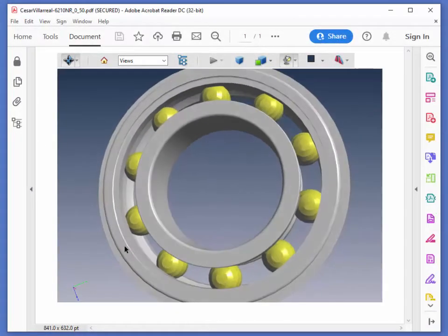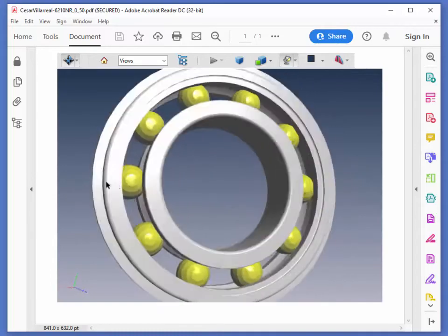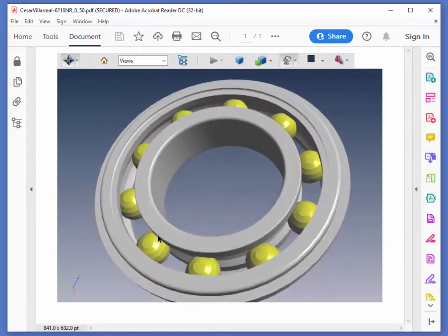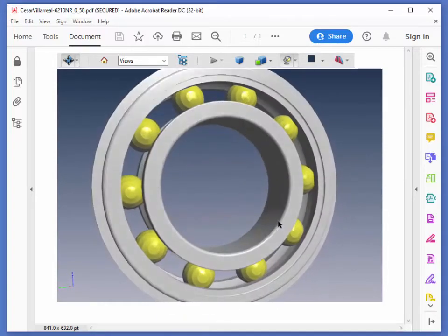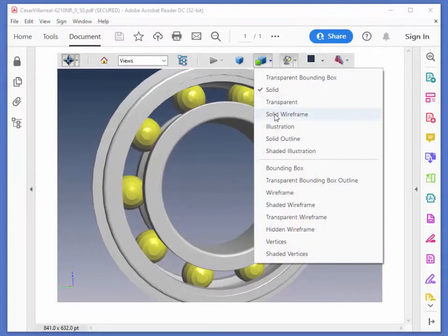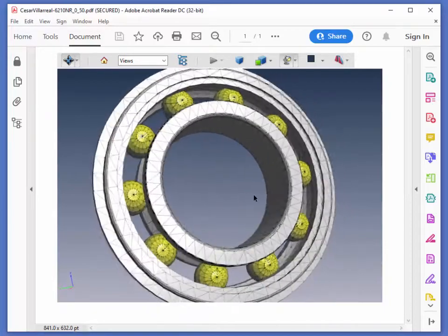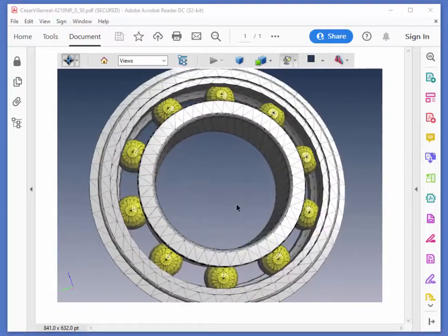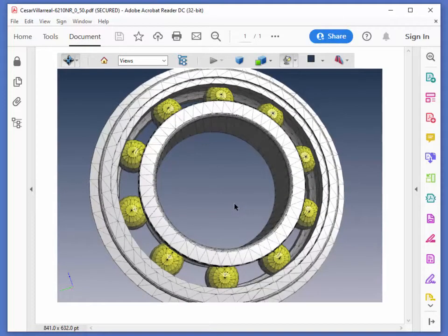In this version, there are several new features that support loading and converting of CAD files, transforming those into 3D PDF, STL, and GLTF. In this example, we have a simple conversion of a step CAD file. And if we look at the wireframe, we can see that the tessellation has been defaulted over the whole surface according to specific curvature. In this version, we've added additional processing options to configure this in a more detailed way.